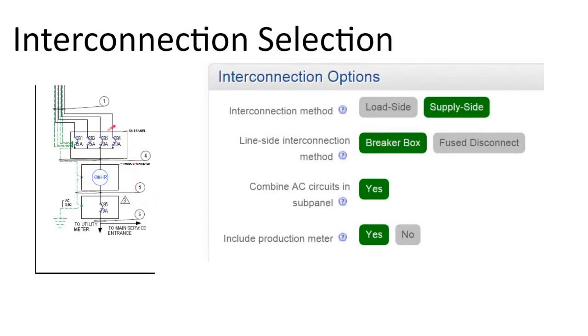And so here we are. What it's modeling is our sub panel with the microinverters all landing on different branch circuits, and then tying into a solar production meter, going through a main disconnect breaker, and then heading out to either the utility main service panel or the utility meter, because it's been denoted as a supply side connection. So these one line diagrams do get automatically generated at some point in the chain.